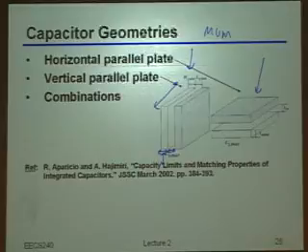Ah, okay. So the vast majority of you got the quote-unquote right answer. Now you have to answer why, though. So why would you use the vertical version? What's good about the vertical version? It seems denser for the same amount of cap, and even though you can't directly control the thickness, you can add metal layers and connect them with vias.